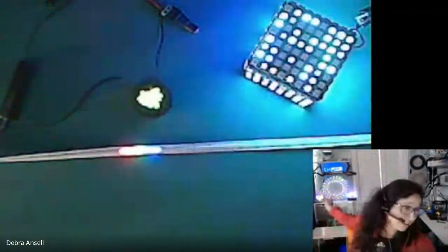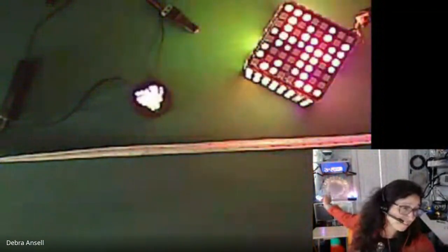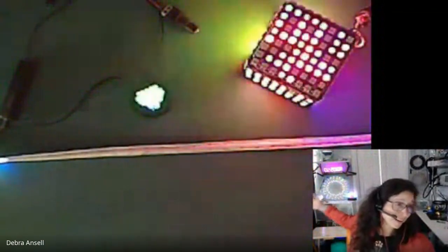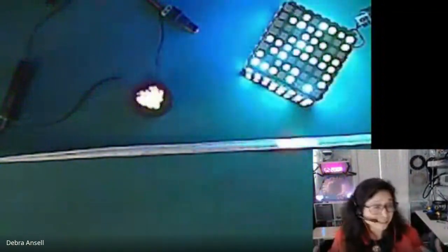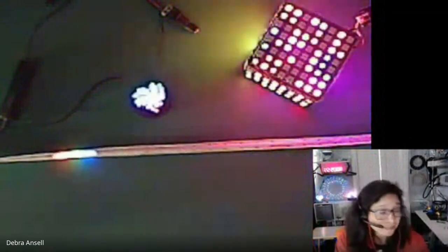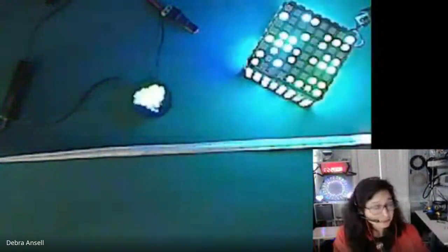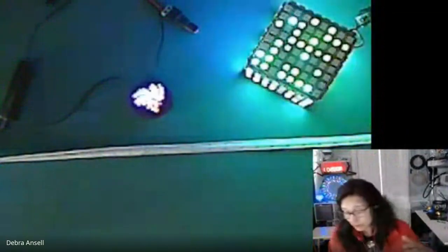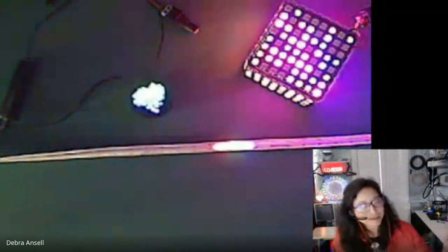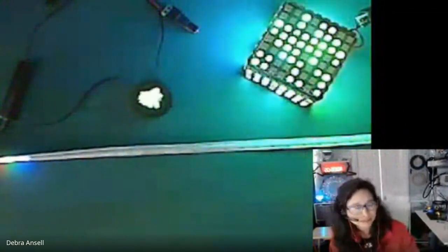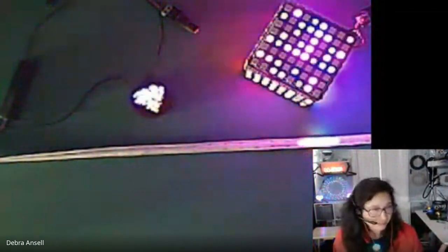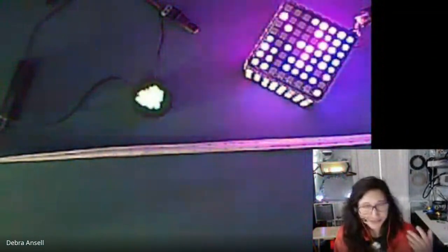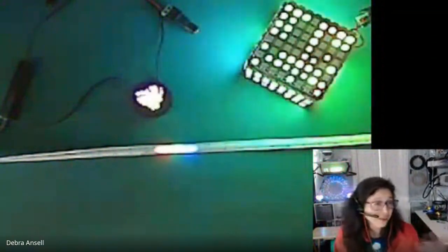And if you see behind me, there's a string art. I've basically taken an LED string and wound it in a circular pattern. And I can run the same patterns in all of these because of the PixelBlaze mapper. The code for the patterns is separated from the actual physical layout of the pixels. So the pattern fills space, and what colors and intensities the pixels display are basically determined by where they are in space.